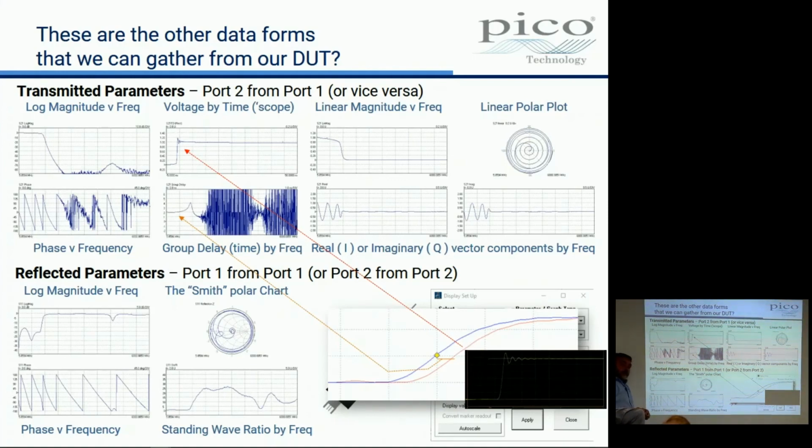And if I was to measure the slope, I differentiate the waveform, that's what this is. It's differentiated phase. And so phase slope is constant, constant, constant, whoops, goes up. Yeah? So that's what group delay is. It's the rate of change of phase. Now, all right, that's a complex notion and it's very hard to get our heads around what that means, right? But let me tell you this.